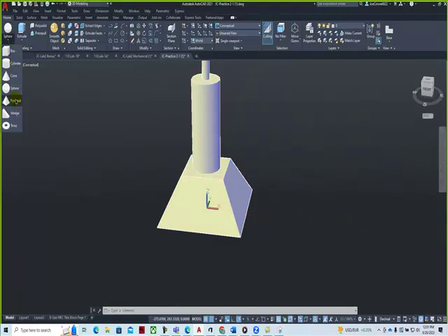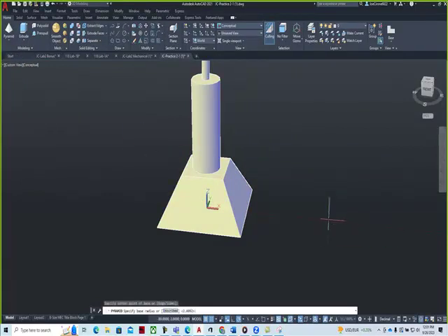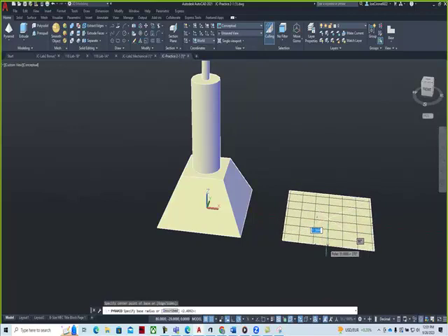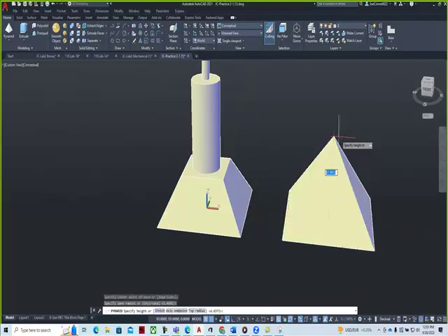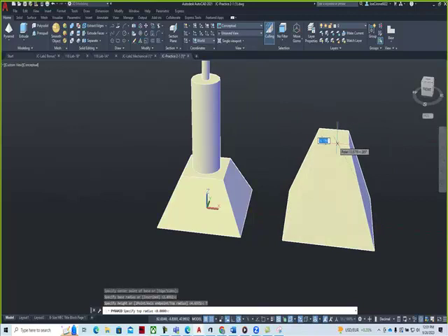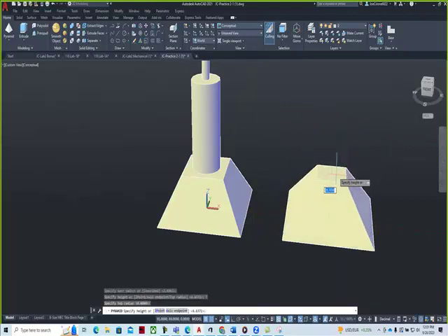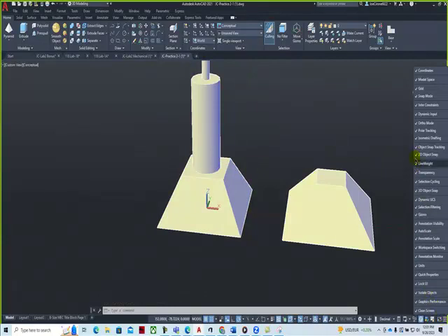and then we're creating the different shapes for things like creating a pyramid. And so as we go and create that pyramid, you can create that shape like this, and then as you pull that, you have different options, and I'm using dynamic input so that I can go through, and so you can change the top radius. This one's kind of flat on the top, so we can say top radius, maybe like that, and then the height, I'm just eyeballing it right now, and you can create those different shapes. And then with dynamic input being on, it gravitates to those different areas.